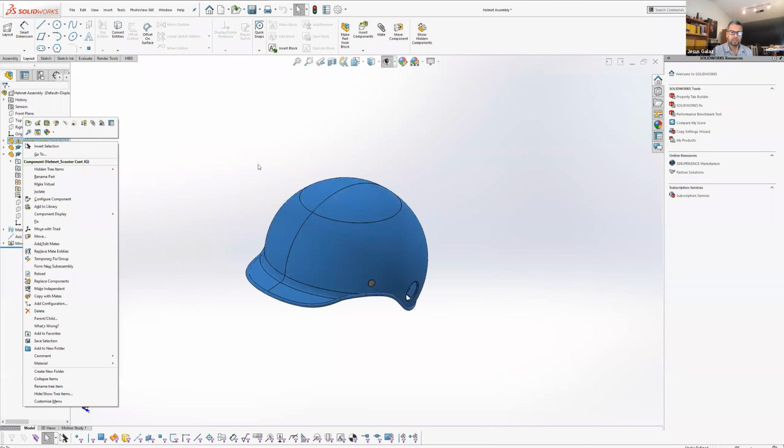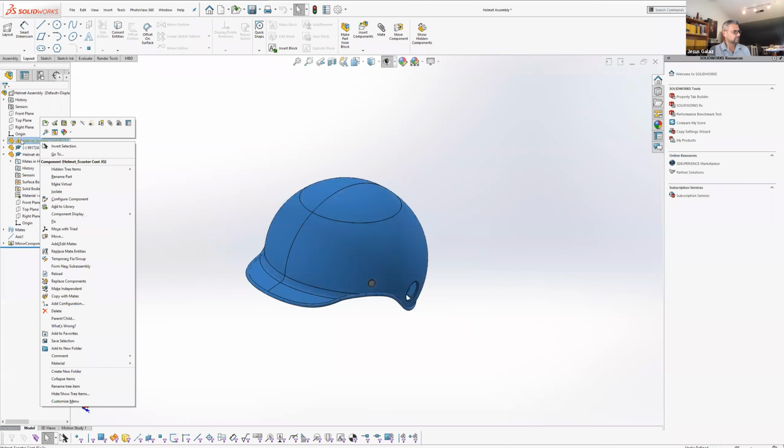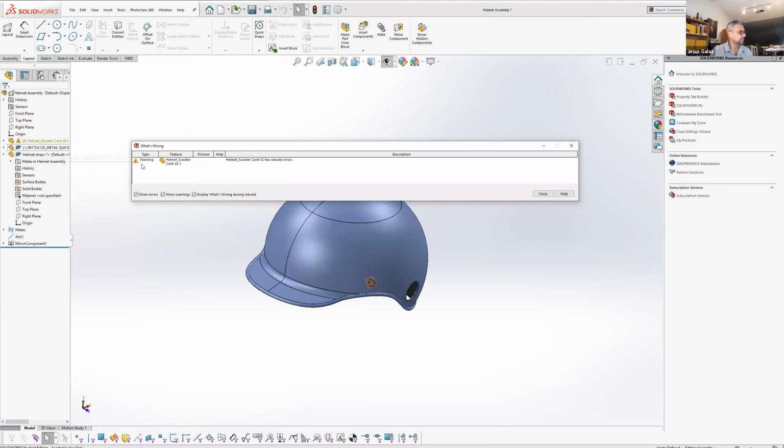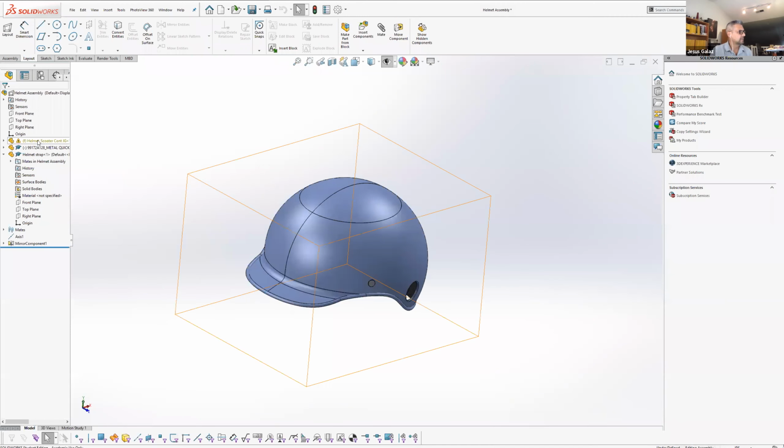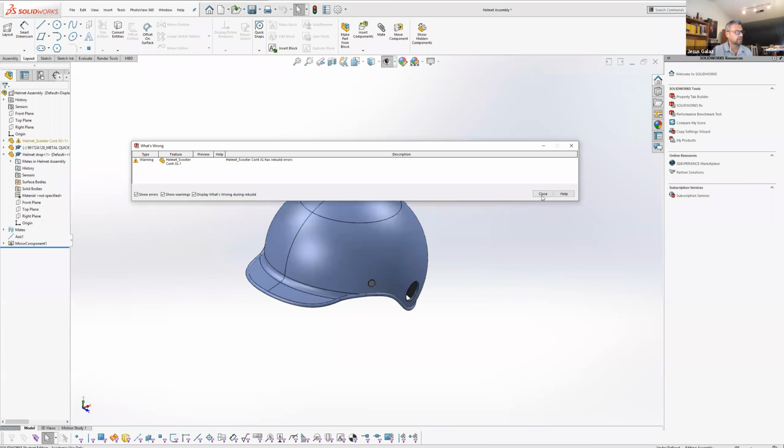Remember the first thing that you bring into an assembly, I know this is stuff from like week 1 to week 2, I think even week 3. Remember the first item is fixed. So you would have to set it to float. Here you can set it to fix again, but it comes in fixed. And then you set it to float when you bring it into an assembly.